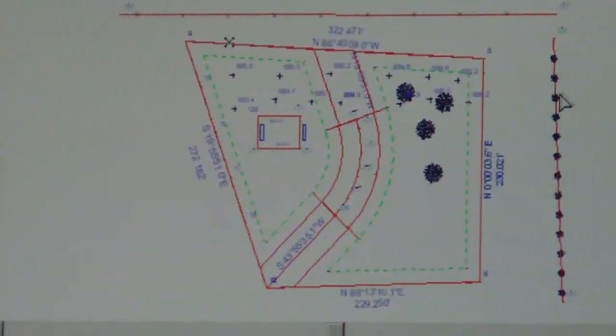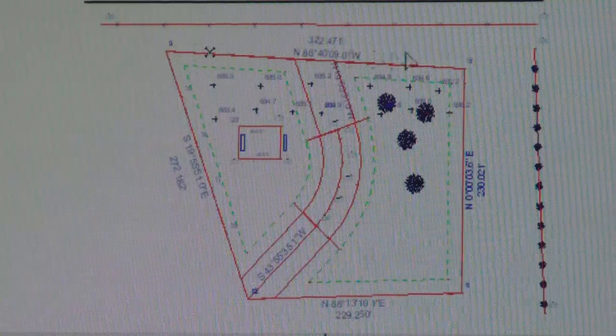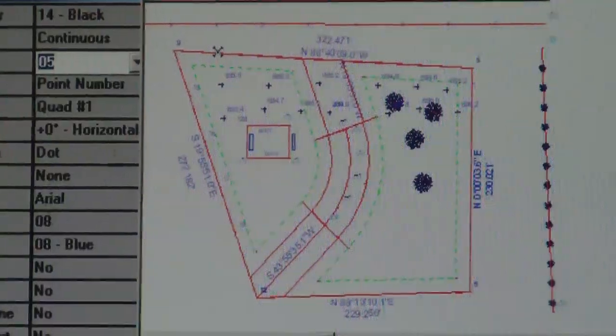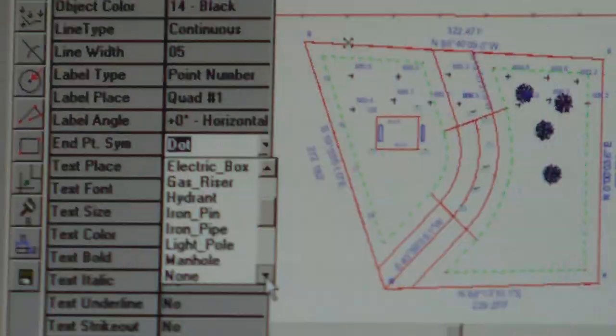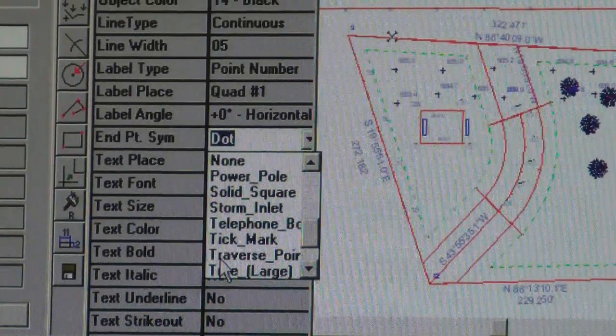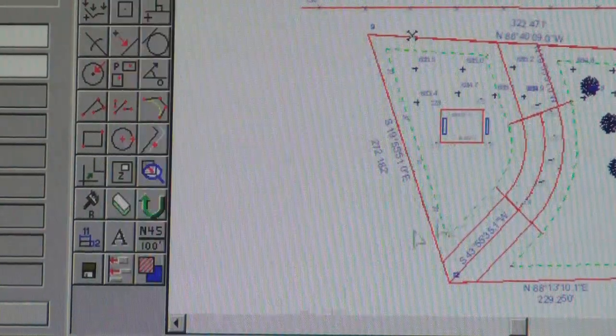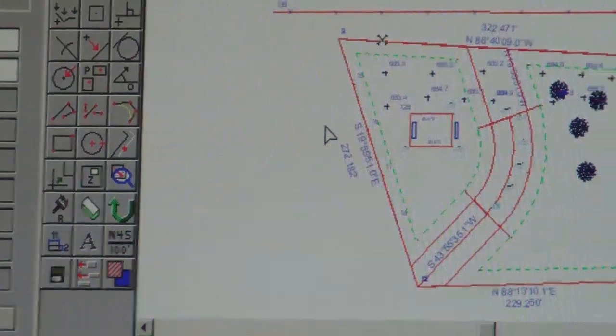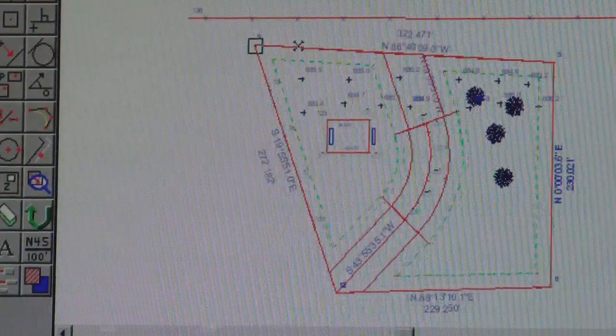And then, let's now go to change our traverse points. They already exist. So I'm going to go down and find a traverse point. Again, if I type in GP for get point, I can go to, click there, and accept it, and it changes.